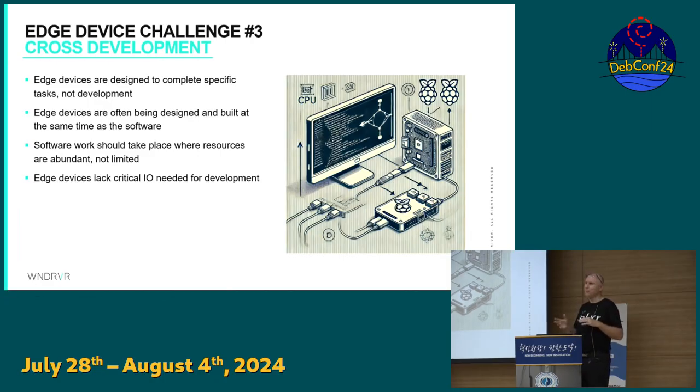And then you're going to take your images and deploy them to your target. If you bring into the mix the fact that you have different CPU architectures, you basically need a cross-development environment. Most of your desktops and servers that you have nowadays are going to be Intel, possibly ARM. And again, your target device might be MIPS or PowerPC. So you need a cross-development environment to support them.